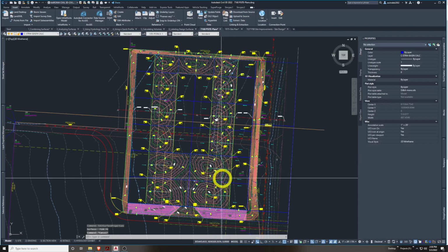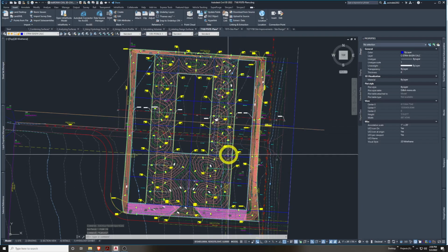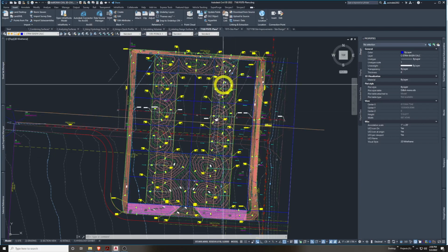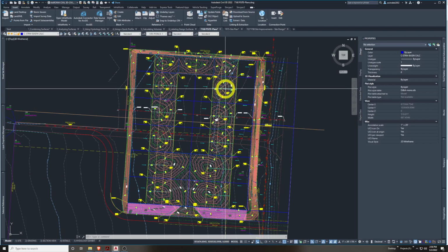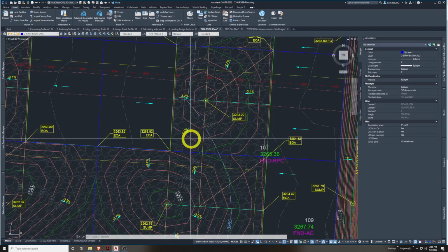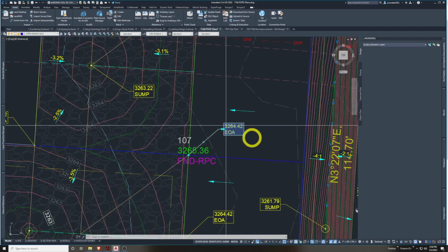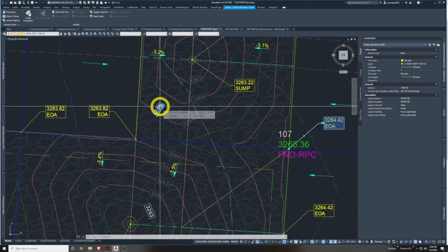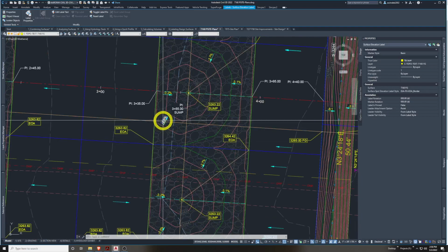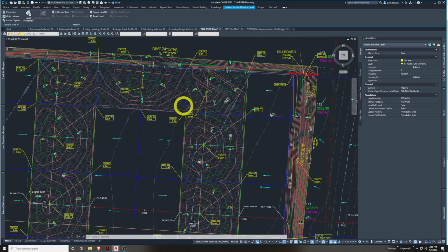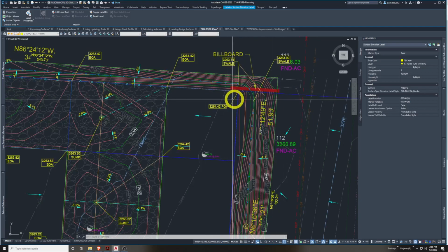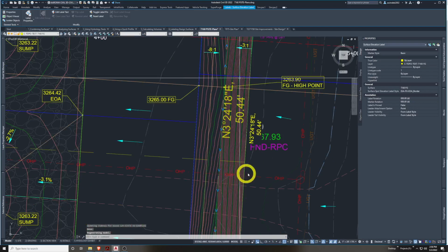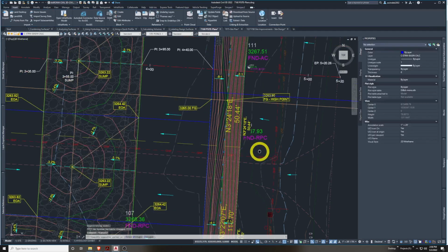I pick a point and say this whole area is a watershed or a catchment. It's an area that drains into itself, where any drop of water, in a theoretical zone, would go to one point. Catchment area or watershed area. And this is just me grading this out, and I have my surface labels here. My surface contour labels showing the contours, and my surface slope arrows showing general slopes, perpendicular, and the one directionality function. I have a lot of grading objects out here where I graded some ditches at 3 to 1 and 8 to 1 slopes and various things moving along the building to create a drainage ditch here on the outside.